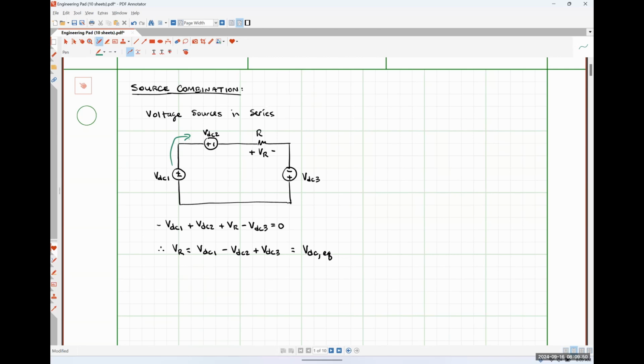So for those of you who may have put a battery into a battery pack or something like that backwards and ever wondered why the remote cares, well, if you have two AA batteries in a remote control and you put one of them in the opposite polarity, the voltages of those two batteries cancel each other out. There is no voltage being applied to the circuit, or a very small voltage, because the chance of the two batteries having exactly 1.5 volts is effectively zero.